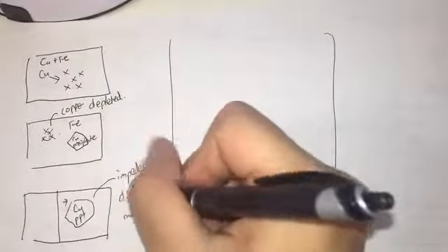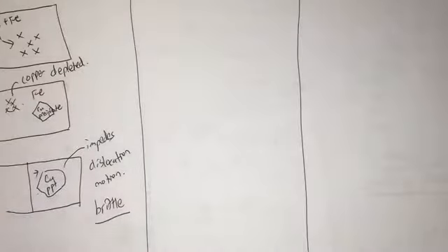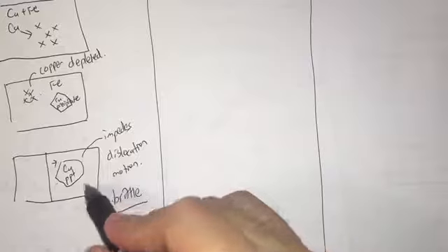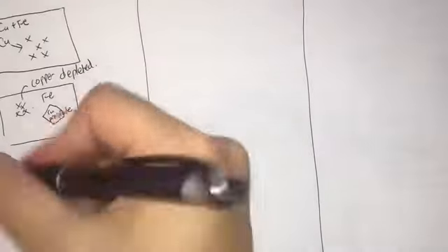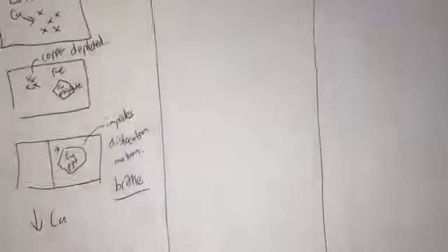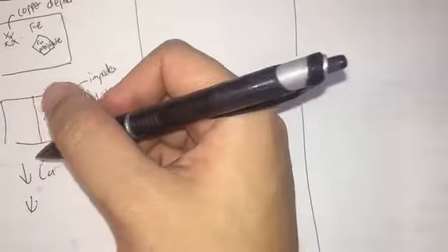And as a result, since we are impeding this dislocation motion, the whole thing becomes more brittle. In fact, this is a very big problem that can cause reactor embrittlement. So big that it's one of the reasons that you want to reduce copper content in the steels. And not only that, we want to lower the nickel content as well in some of our steels.